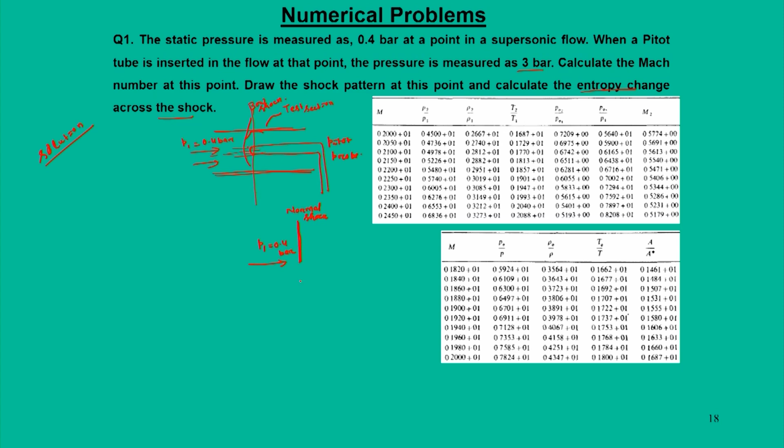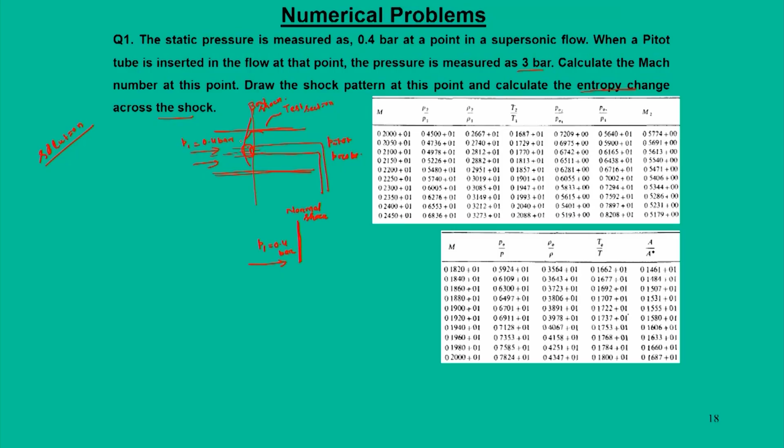Since it is a shock wave, when the pitot probe and the flow comes and sees this particular point on the probe, as if it becomes stagnant for a particular instant. Obviously, that means this acts as an obstruction in the flow field, as if for a certain flow time the flow becomes stagnant. So, for that case, this pressure which is measured here is to be regarded as P naught 2, that is stagnation pressure after this normal shock, and that is the catch here, that we must say that this pressure is 3 bar, that is stagnation pressure. So, basically we now know this number.